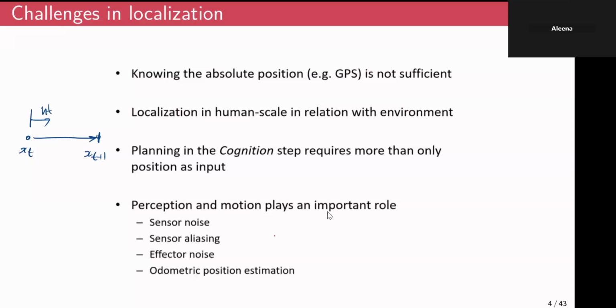So what we do is we rely on multiple sensors for measuring a single parameter, and then we fuse the data from all the sensors to have a reading with lesser uncertainty, right? As you are getting more and more information from different sources, the uncertainty basically reduces, because it's something very intuitive to understand.